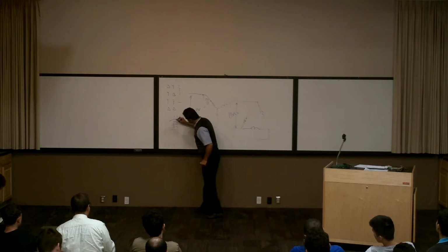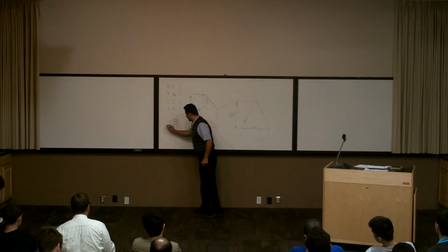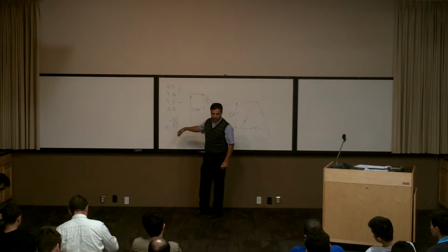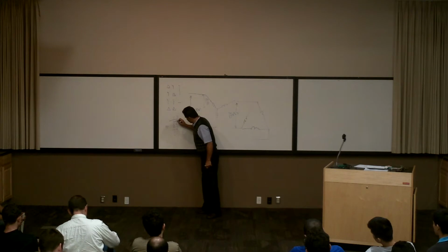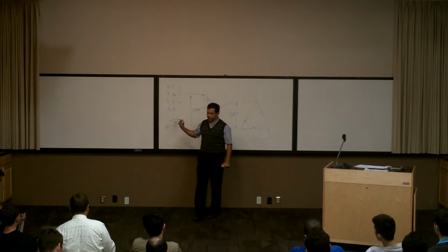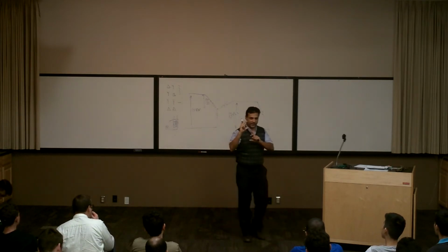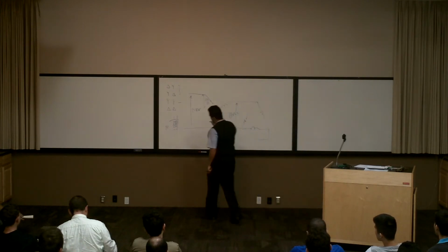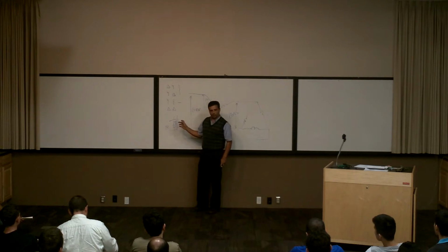See, between this wire, there is a voltage, right? If I have 130, for example, here, and this is 10 turns, for example, between each of them is going to be 13, 13, 13, right? I have 13 between every two wires. So 13 volts is very small voltage, and there is no problem with the isolation.